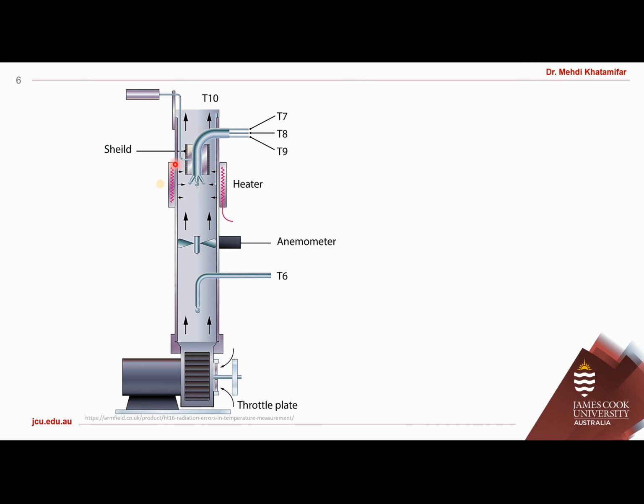Around the cylinder we have this heater, or heated area, so we are heating the metal cylinder in this area, and our controlling system controls the wattage and current of this heater, so we can increase or decrease the amount of heat we are putting in here.